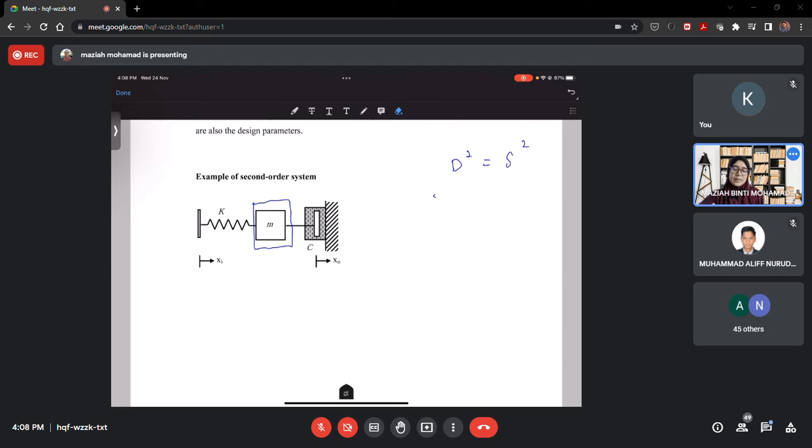In order to get the time response equation, we do all the steps again: first produce the ODE, second transform the ODE into Laplace form, apply the initial condition, apply the input, partial fraction, solve for the parameters using the remainder theorem, and lastly inverse the Laplace to become y(t). y(t) is the equation that describes the behavior of the second order system.